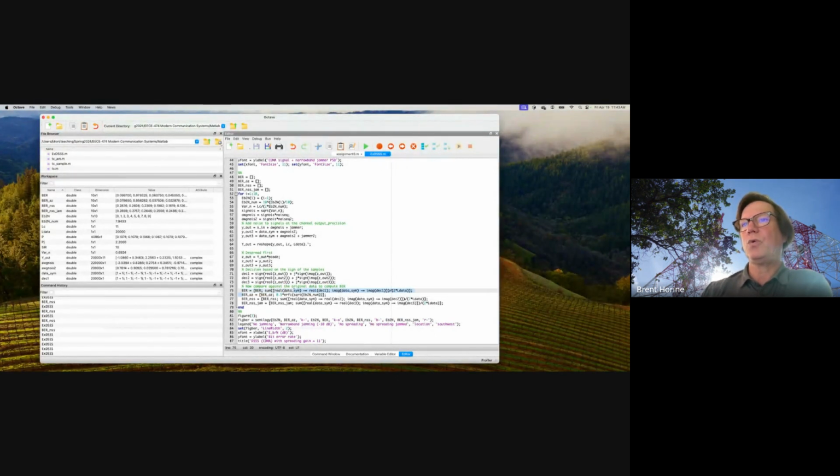Then for the basic case, they're using this erfc function, which is related to the Gaussian function, to actually print out the theoretical performance you should get. And then I've added the situations of a non-spread basic QPSK performance, and also the jammed version, and then we plot that.